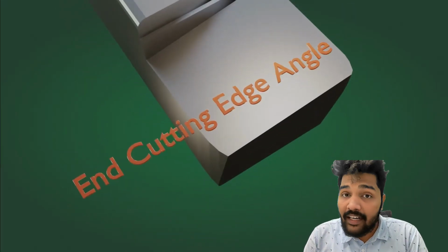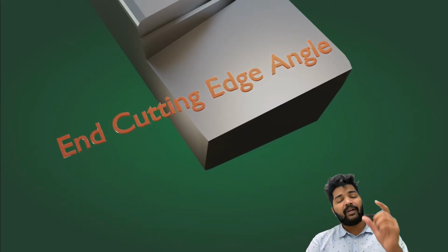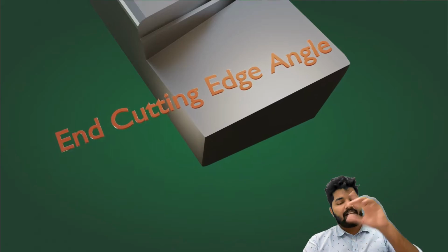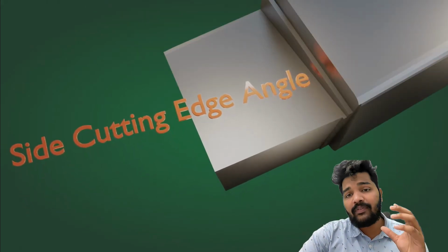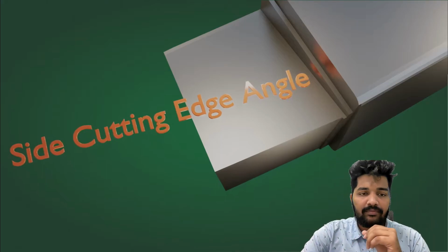Fifth, we have the end cutting edge angle. Now this is the angle between the end cutting edge and a line perpendicular to the shank. This angle influences the tool's cutting efficiency. Lastly, we have the side cutting edge angle. Now this angle is between the side cutting edge and the shank. It affects the tool cutting action.